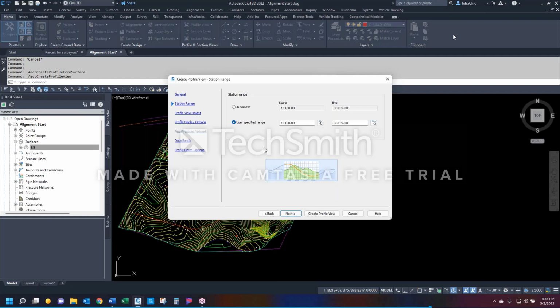I might have a grid that's way too long to fit on one sheet. Maybe I can only see 600 feet of the profile or 1,000 feet of the profile. If that's the case, this ending number is not going to work. It's going to completely go off the sheet. I'm going to lose the right band where it says here's my elevations because it's too long. But you can make multiple grids and share, and in those multiple grids, have one and only one surface line in that same grid as you would in another. And I'll show you that in a second.